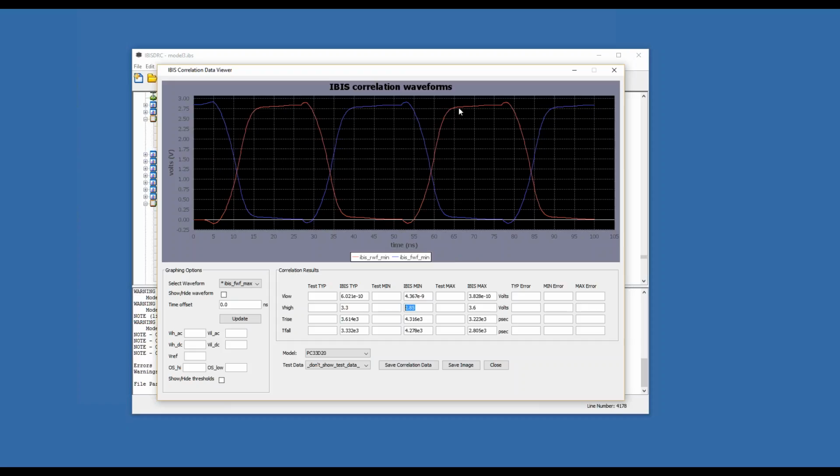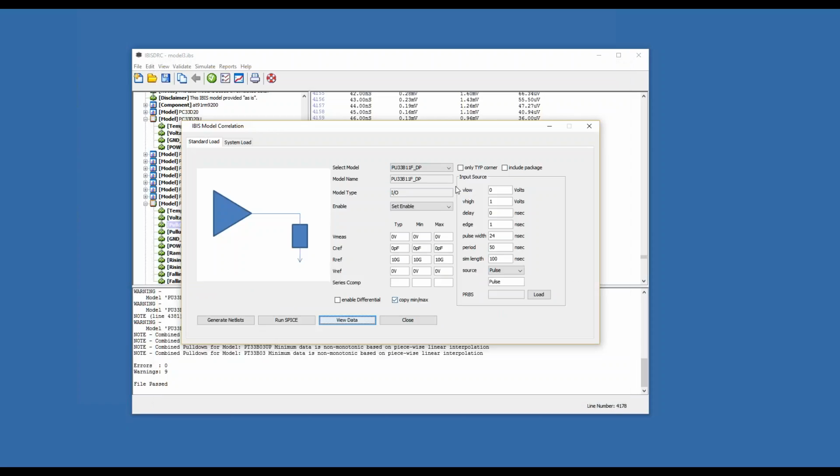You can see that it's having a little bit of trouble driving up. There's kind of a glitch here, but things like this you really can't tell whether this is an issue or not without correlation data. So if you had a lab snapshot from your own bring-up board, silicon validation board, evaluation board, you could see that this is what the circuit would look like. But ideally, the IC vendor would give you some correlation data for this, right? They would show you this data, the test loads, and you can see waveforms, say, overlaid, right?